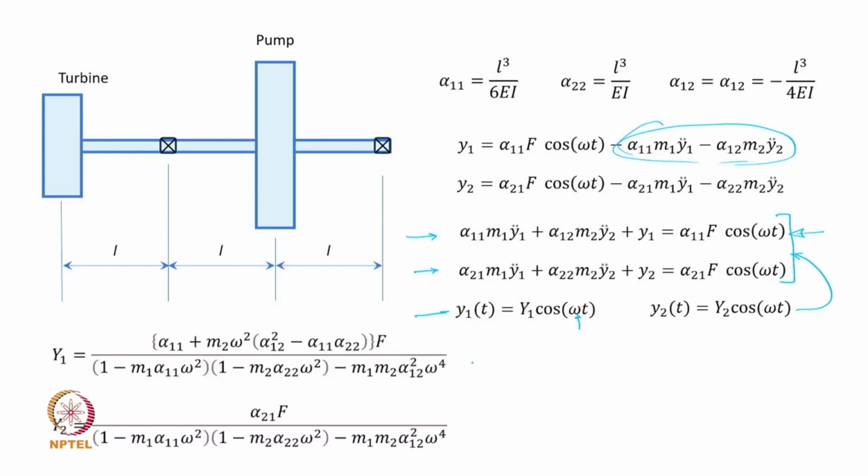And obviously, these are all what? These are the responses to harmonic excitation. It will be dependent on the magnitude of the external force obviously, and both of these are dependent on the magnitude of the external force F, and if unbalance is considered, then F is going to be u into omega square, where u is the unbalance which has the typical working units as kg millimeter.